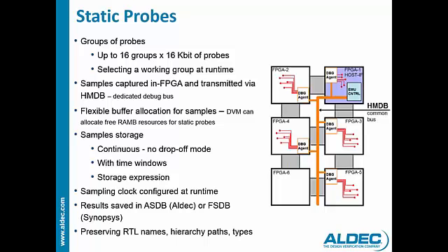The signals are captured and transmitted via a common bus, which is transmitted down to the local host computer. Depending on the memory storage required, the verification manager can free up internal RAM blocks and allocate them to static probes. These are these little debug agents.